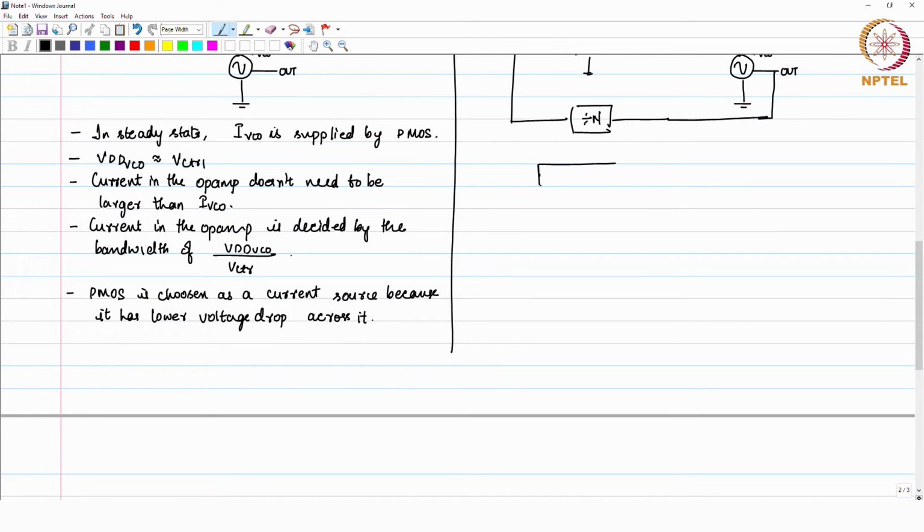Okay, so just remember, we need to add transistors when we need, not just because we have the space and we can add transistors. Okay. So, this is a simple amplifier with Nmos input and Pmos as a load. It has differential input, and so this is V bias N, you can say. This is VIP and this is VIN.